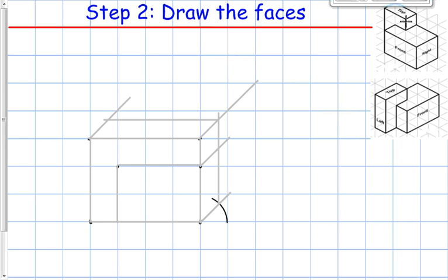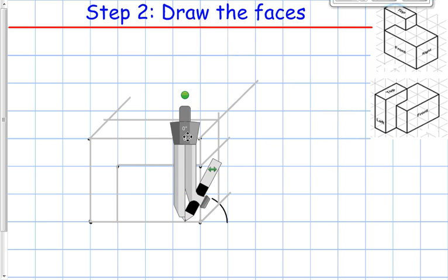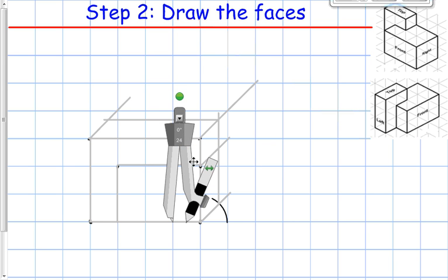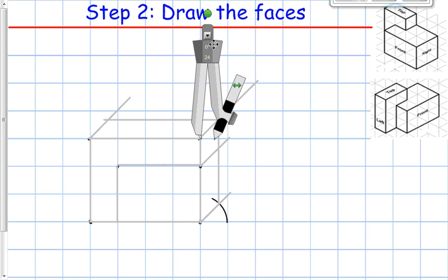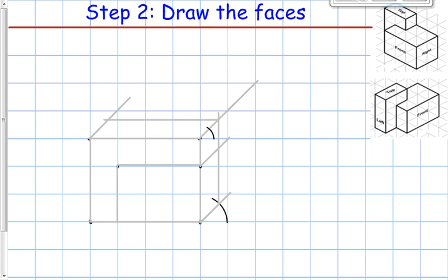I see that this top portion is about halfway back of the depth. So I'm going to count back. It's going to be about halfway here. I could use my compass, which actually we will do because we want to keep things correct. So I'm going to move it. And this time we want it to be a distance of half. Since we cut the distance in half already, and it's only a distance of halfway back, we're going to mark it right here. We're going to have its line go right there. So that's where my construction line is going to be.